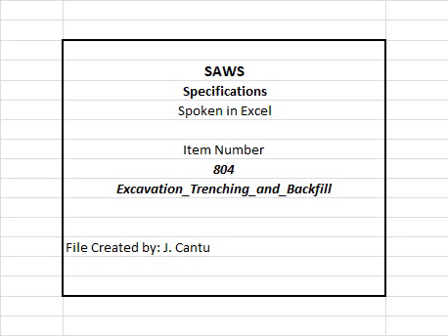1. Any failed test shall require the contractor to remove and replace that layer of backfill in the identified section of the failed test location to the trench depth and a length 50 feet in both directions, then refilled and compacted to the grade and compaction level required. 2. The contractor will also be required at no cost to SAWS to provide 2 additional tests at the replaced location where the initial test failed and at one location point, randomly selected or as indicated by the SAWS inspector/test administrator.